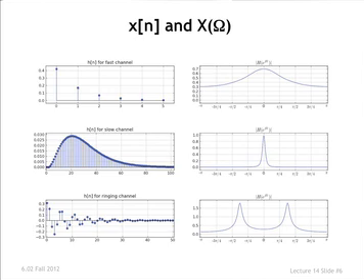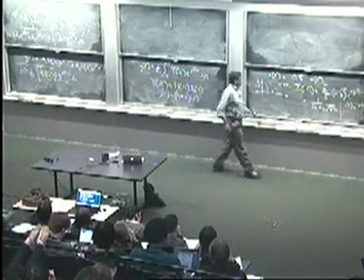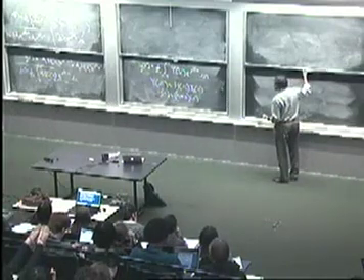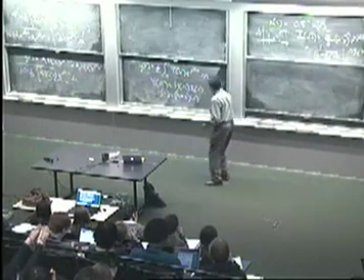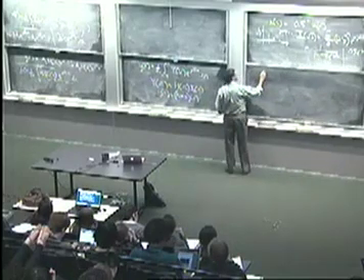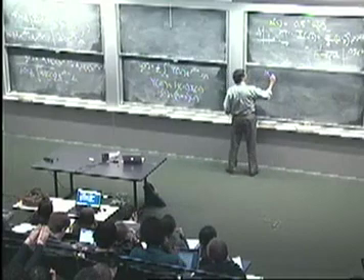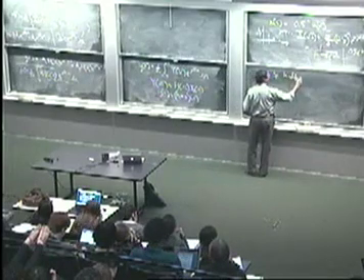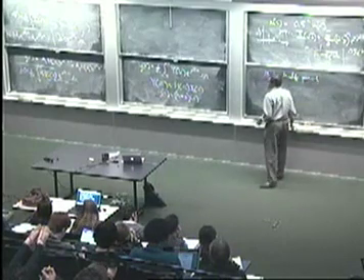About how long does it take, if you were thinking of underlying sinusoids, what's the fastest wiggling you're seeing over here? Well, to my eye, this kind of rises and curves within about 18 or 20 samples, right? So this might be a half period of an underlying sinusoid. These are just rough calculations, but it helps you understand what we mean by spectral content and helps you as a way of checking answers. But let's see, if I said 18 was approximately a half period of an underlying sinusoid, and I don't see anything faster than that.